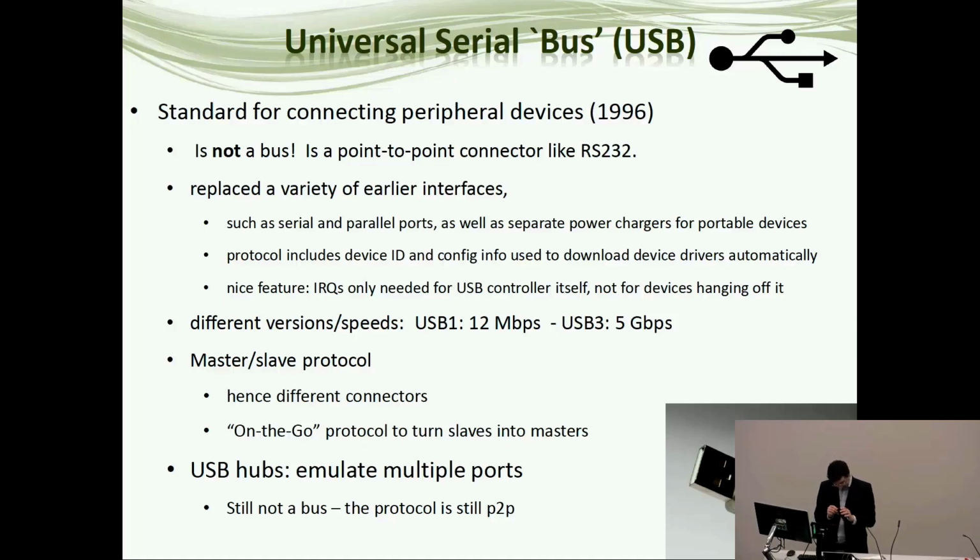So it's the reason why it's a little tricky to say run a desktop PC's USB sound card off your phone. Again, if you want to do computer music on your phone, you need to turn your phone from being a device into being a master. So you can do this. There's something called the on-the-go protocol that turns slaves into masters. You can make this in charge of the USB network, but you'll need a physical thing to plug in there and swap the directions of the sockets over.